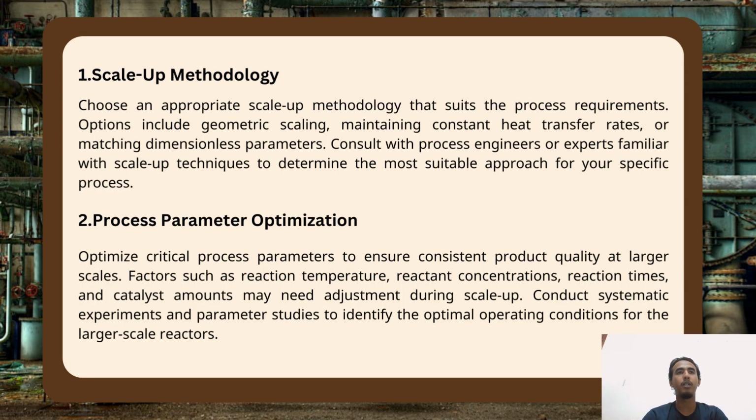So for the problems that we raised from the process, we have certain ways to improve it. First of all is the scale-up methodology. It's important that we choose the right scale-up methodology that suits the process. It includes geometric scaling, maintaining constant heat transfer rates, or matching dimensionless parameters. Consult an expert to determine the most suitable approach for your specific process.